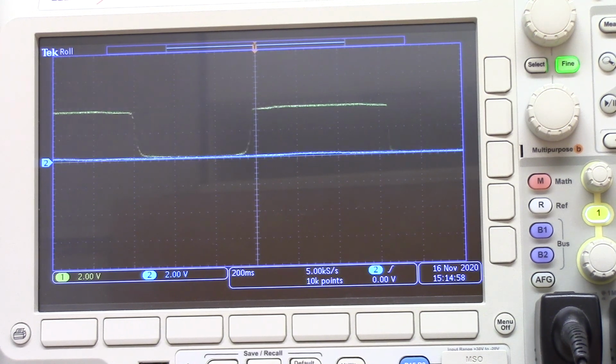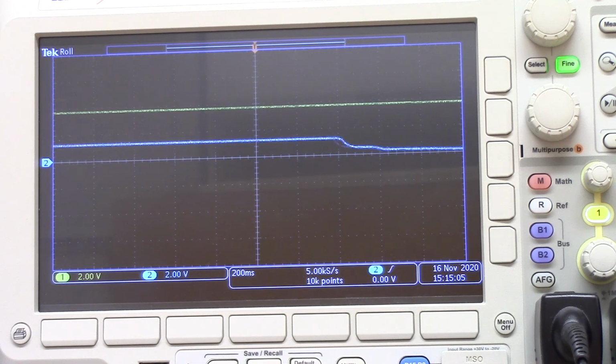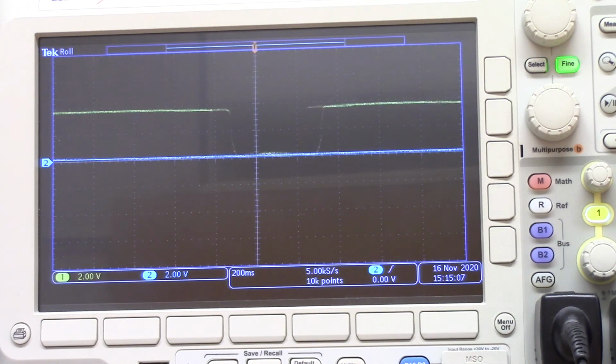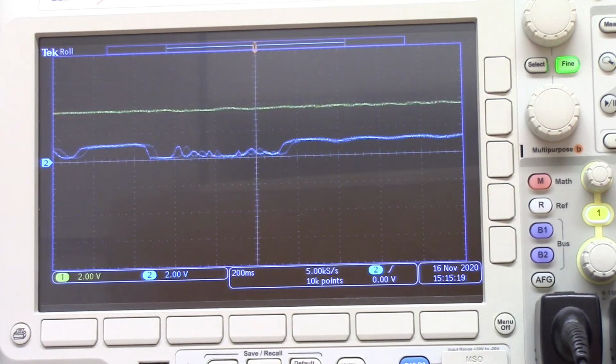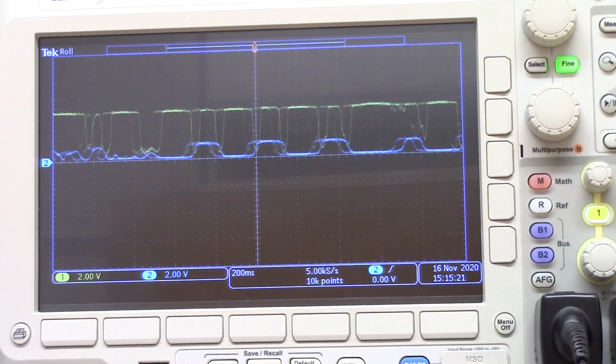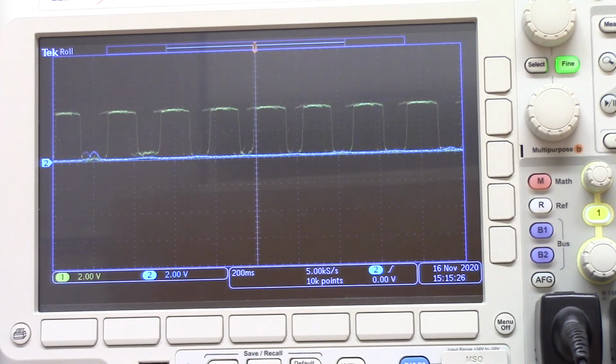So you can see the increased gain of the Darlington transistor narrows the bandwidth of response. It's only a relatively small change in light at which it saturates. It goes from fully on to fully off. I can just wave a couple of fingers over it. I can just wave my hand over it and get this kind of fun response.